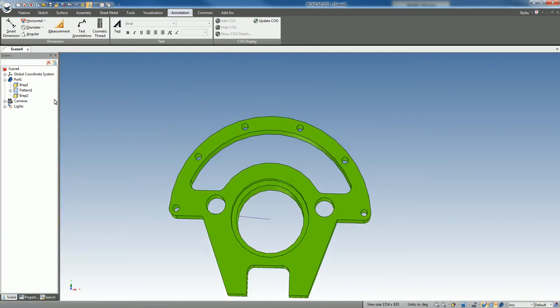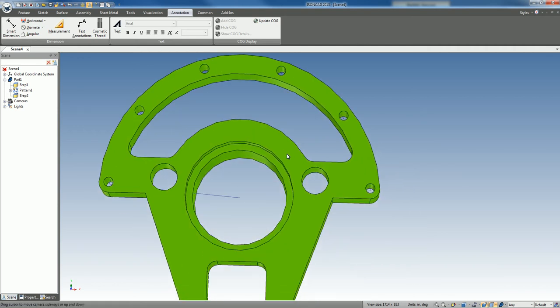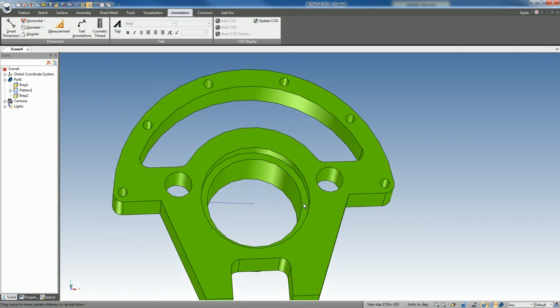Okay, ideally in the future we would like to have an option possibly here, similar to what you can do in Structure, that you can maintain the features and also do a direct editing as well. So you could actually edit the cross section, then reapply this edit face radius, for example. So that would be something we would like to enhance in the future, but you can see the benefits of both in this example. But again, you don't need the features to do a lot of modifications.